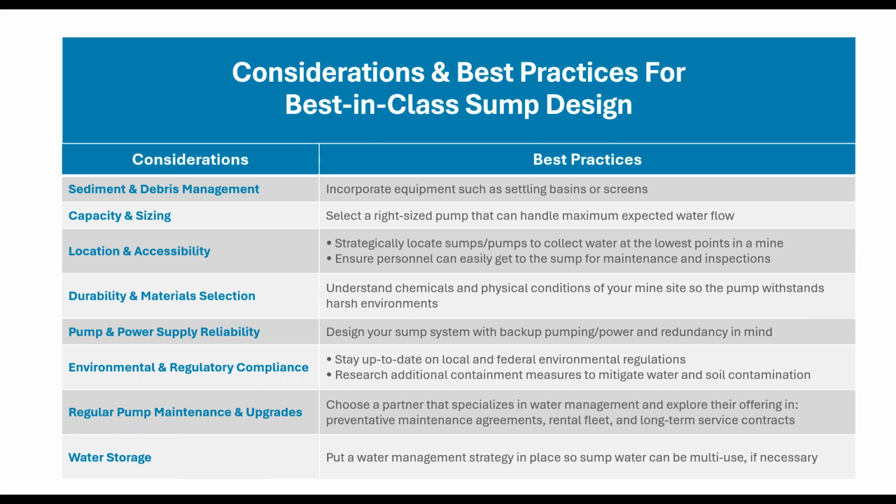Start at the lowest point of the mine to start our dewatering pumping process and system. In addition to the location, accessibility for the maintenance and upkeep. That could be maintenance and upkeep of the sump itself for inspection and that sediment removal that I mentioned earlier, but also access to enable the servicing of pumping equipment, making sure that it is operating at its optimal, most efficient points.